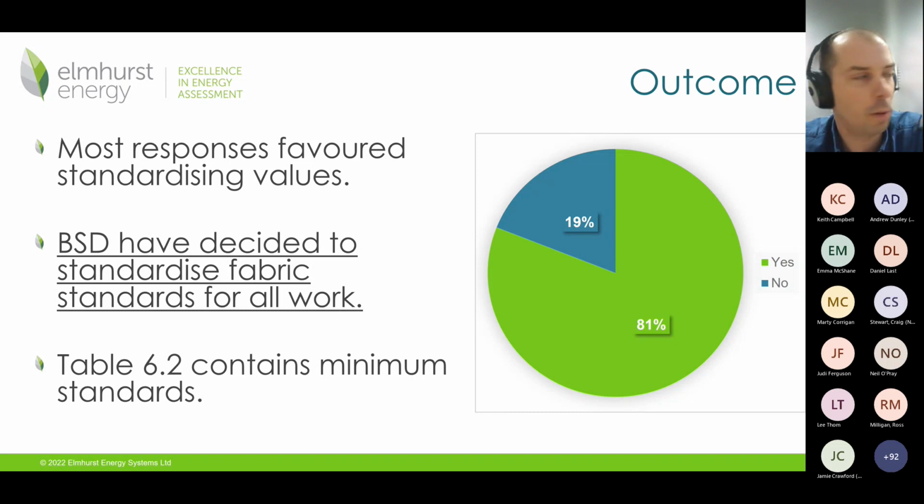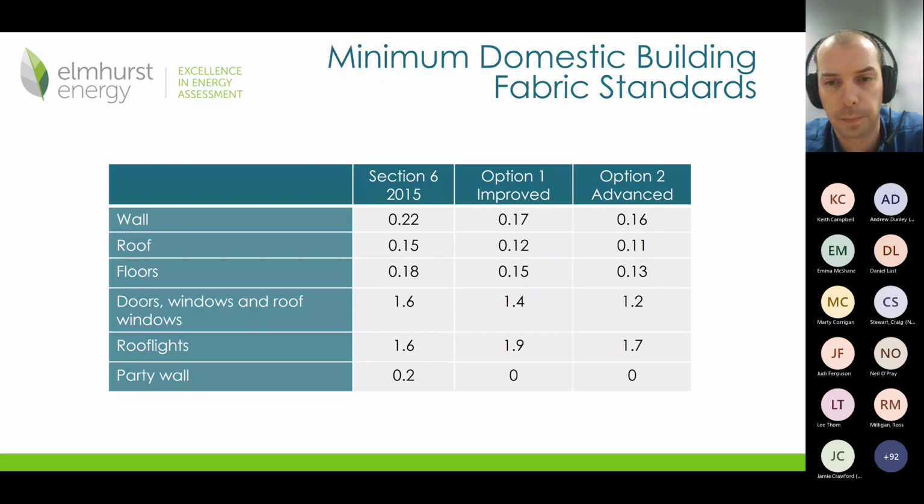Okay. It's general comments where it was providing clarity and a better understanding of the requirements, but there were some concerns. Obviously, those U values are pretty ambitious when you talk about conversions, for example, and you're working with an existing building envelope. That could be pretty tricky to achieve. Okay, that might be where the space heat demand method comes in, where you get a bit more design flexibility as well.